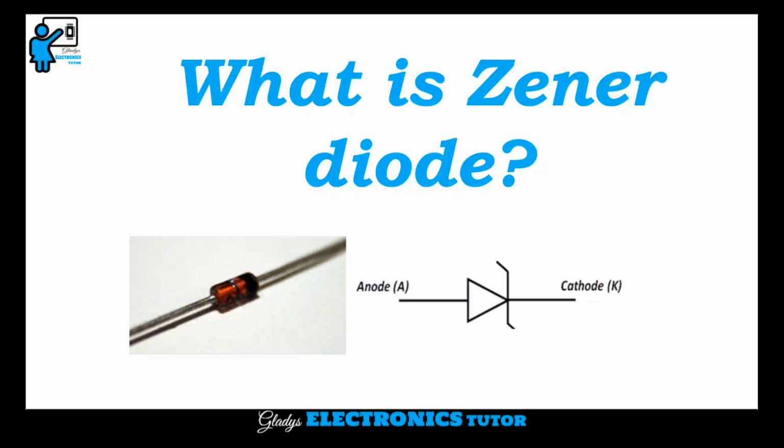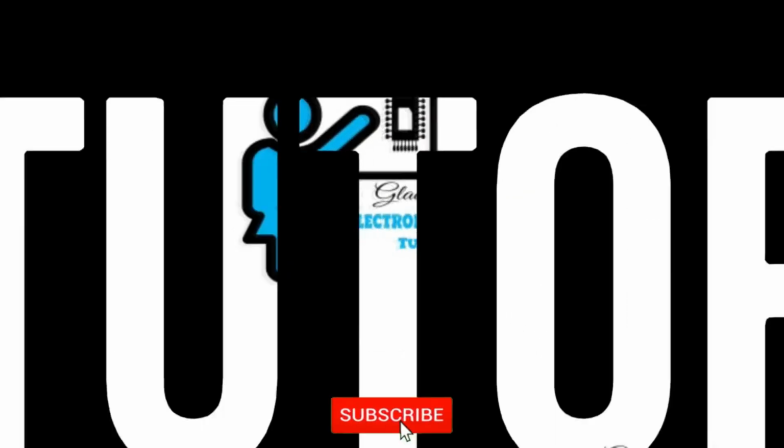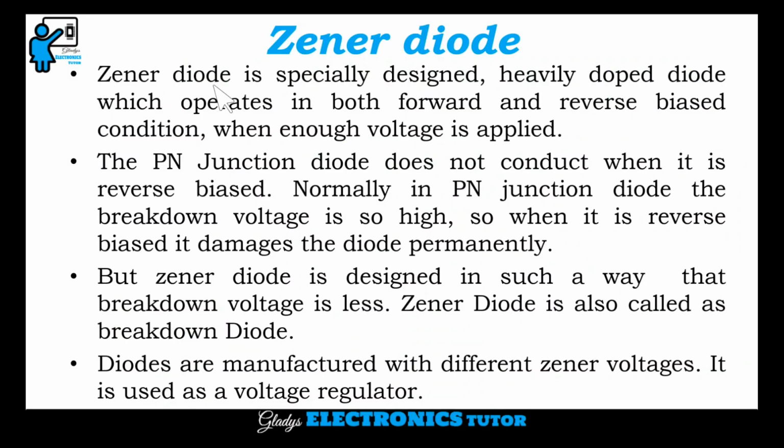In this video, let's see what is Zener diode. Zener diode is specially designed, heavily doped diode which operates in both forward and reverse bias condition when enough voltage is applied. The PN junction diode does not conduct when it is reverse biased. Normally in PN junction diode, the breakdown voltage is so high. So when it is reverse biased, it damages the diode permanently.